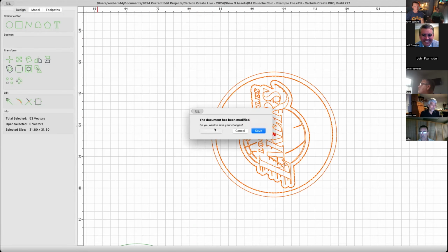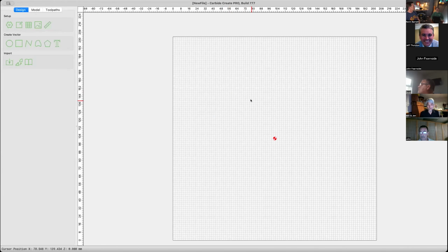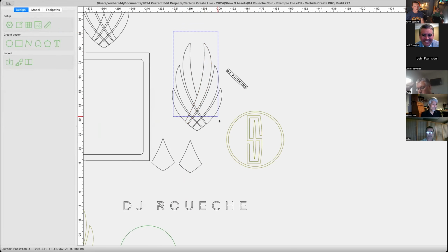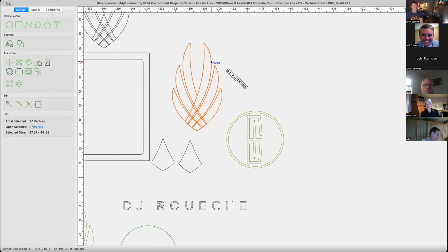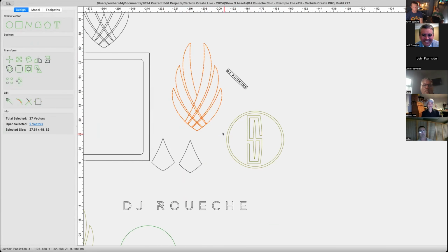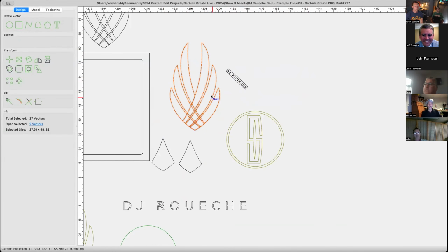If there's one set of hotkeys I can suggest to get comfortable with immediately, it's group and ungroup. Yeah, so great call. G and U. You select a bunch of items, you hit G to group that set of items together, whatever is orange and highlighted. You can select a group of objects and hit U to ungroup them. And man, getting the hang of those on the fly helps tremendously when moving large amounts of objects or just a set of objects around, especially when you're making toolpaths and whatnot. It's very, very good.